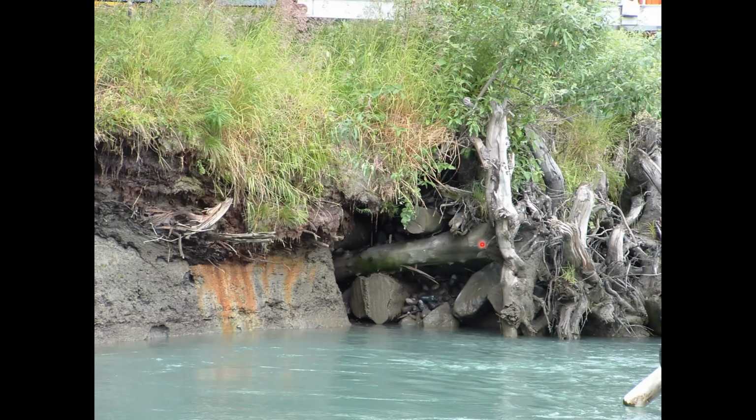The other thing they could do is take this fan, instead of having it face the river, they can start having it face downstream a little bit. So this is the water's flowing from this direction. As you're doing this, think about your tie-ins. You may need to extend the project. Maybe you only need 15 feet of root wads, but in order to get a really good tie-in spot, you may need to go another 20 to 25 feet. So keep that in mind.